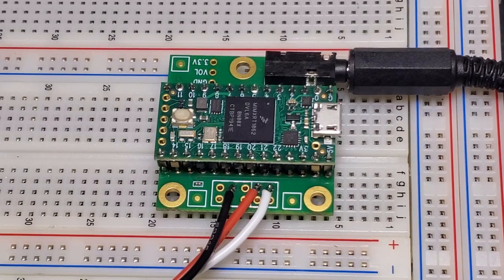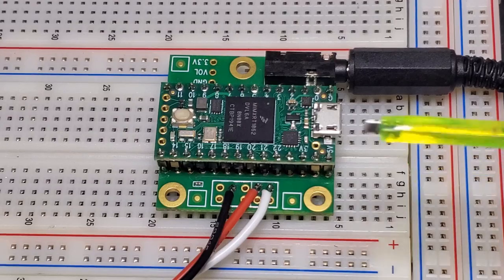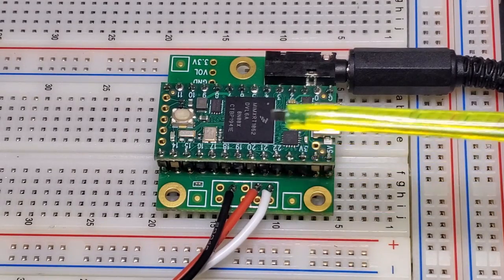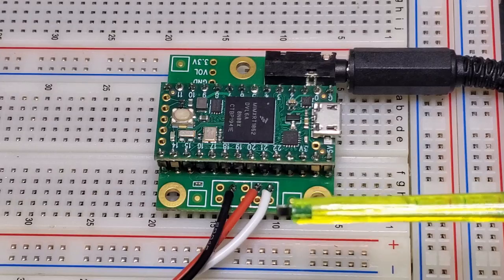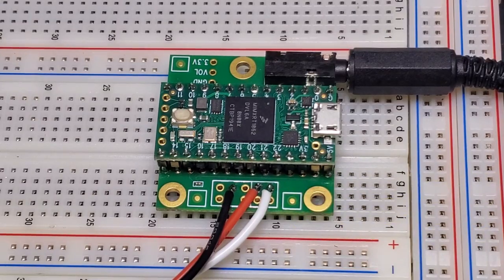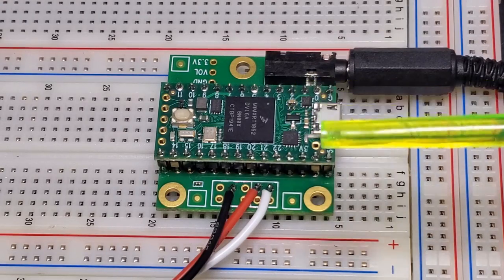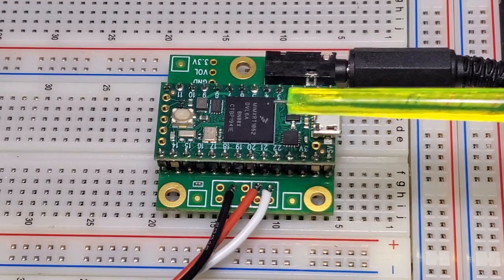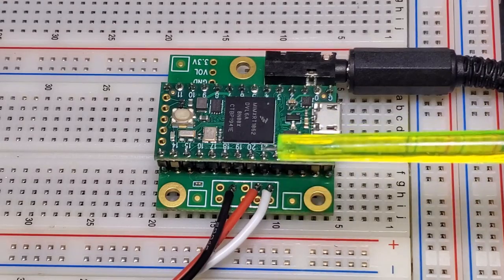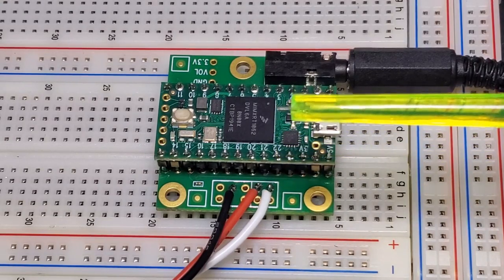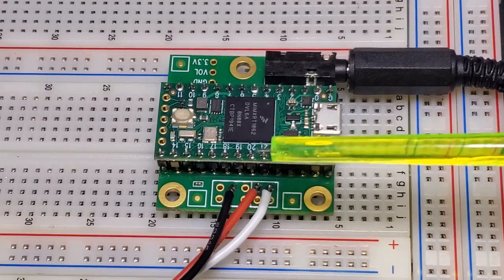But what I thought I'd do is just walk through in this video some of the things that you can do with the Teensy. So I'll show the basic setup, how the Teensy connects to the audio shield, and a simple program that shows I send a signal in and I can receive a signal out. Then I'll move on to how to develop a 90-degree phase shift using a pair of finite impulse response filters and some software that comes from a site called Iowa Hills that allows you to define that.